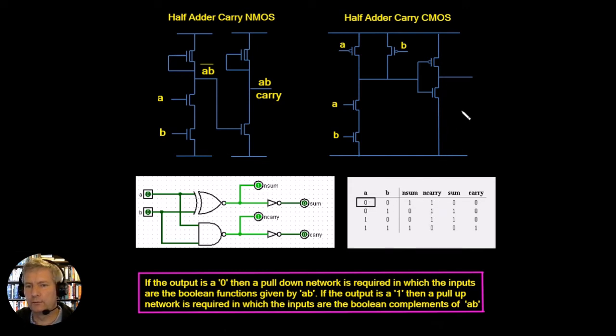So the complements of the inputs are going to be the A B, and that's going to be ORed with the complements of the next input, which is going to be A not B, and finally the complements here, that's going to be not A B plus not A B. So we could take out the common factor between the first one and the third one, which is going to be the value of B.